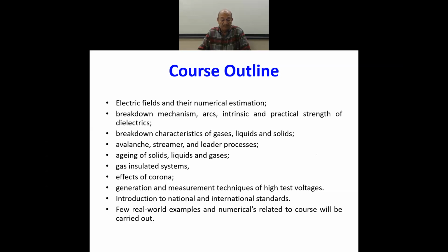Then we'll be talking about the development of breakdown, which begins with the avalanche process, and then it grows into streamer and leader phenomena. We'll also be talking about solid, liquid, and gaseous dielectrics getting aged over time, and how that affects their insulating properties.